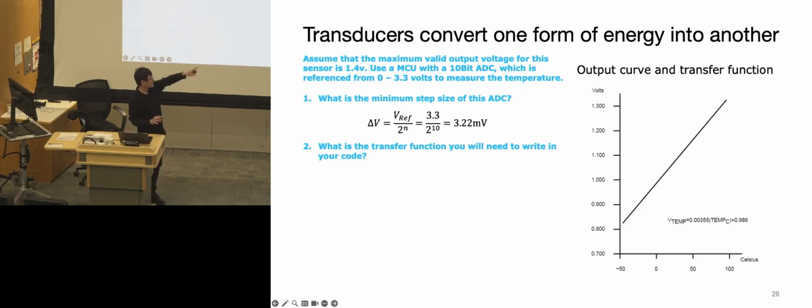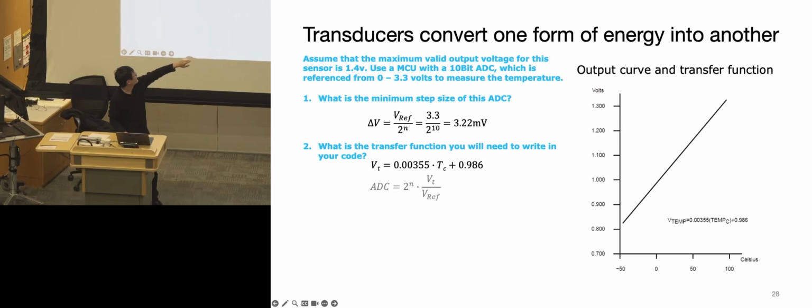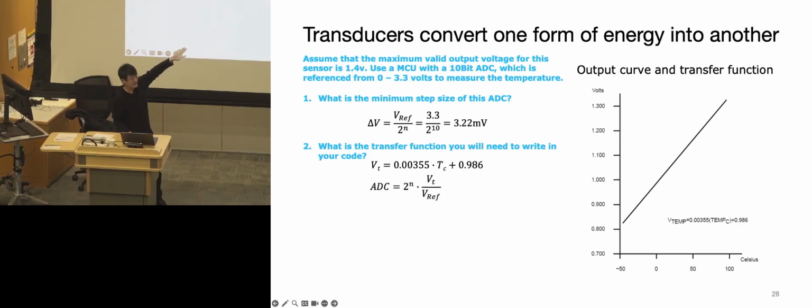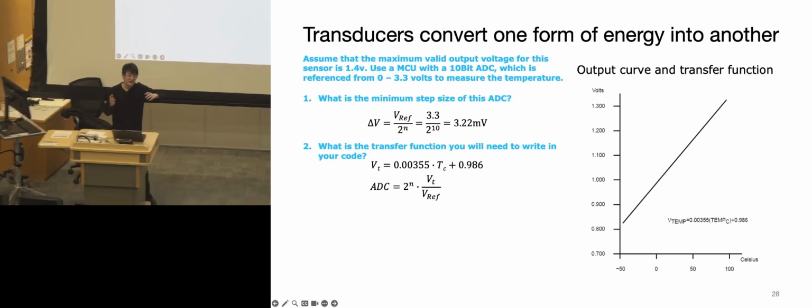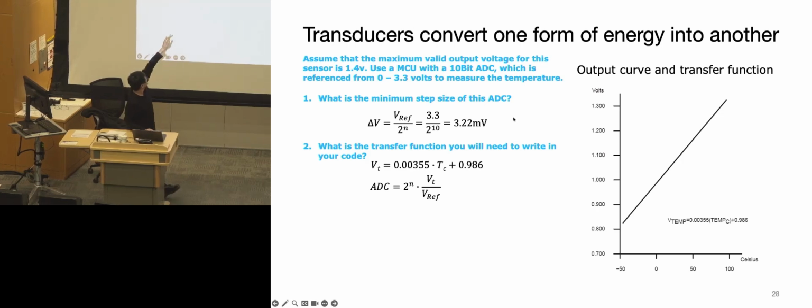Yes, but the V temperature in this case is going to be sampled by the ADC, right? So you have to convert that into an ADC value, and it's a 10-bit ADC value. So that's the equation we have there, and then we have the ADC value. Say we have a 10-bit ADC, and it's usually just an integer. So we have the ADC reading from 0 to 1023, and each number represents a voltage value from 0 to 3.3 here.